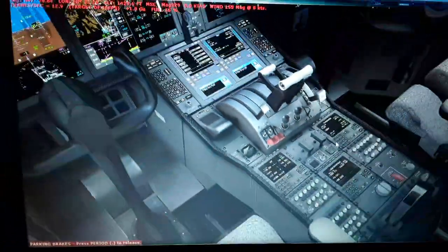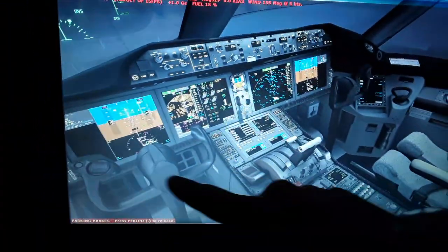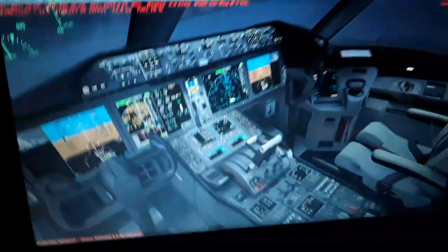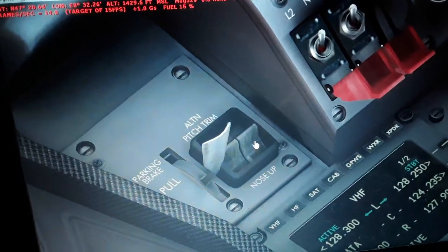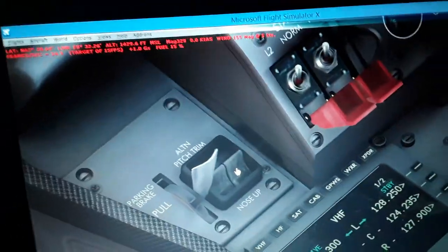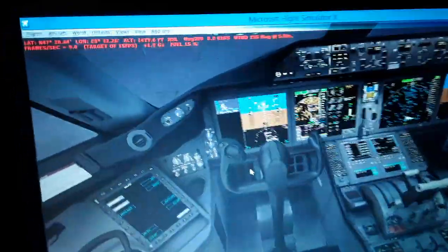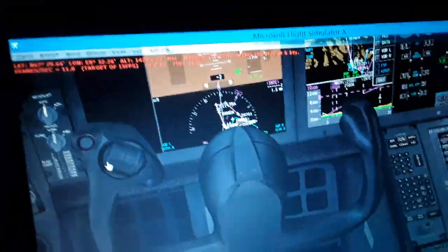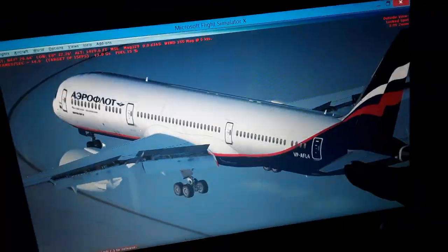It's gonna disconnect the auto trim function from the autopilot flight director system panel, so we're gonna have only the manual trim like this. Here and here the alternate pitch trim from this panel, so you can keep pitch trimming the aircraft like this. I'm gonna show you a few more things. Pitch trim down and up, and you have the elevator pitch moving up and down in flight.